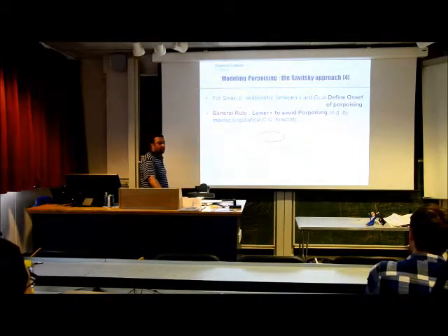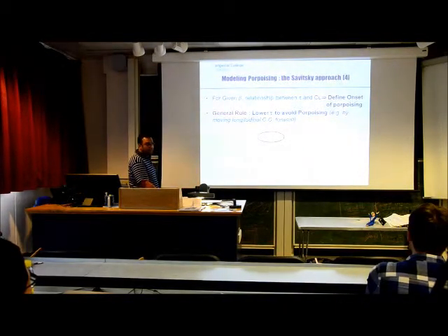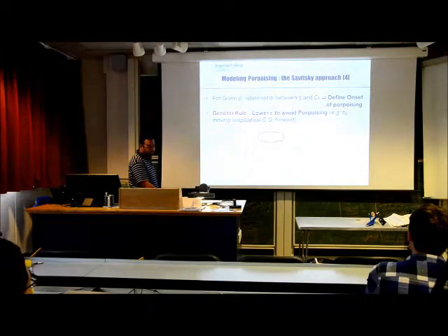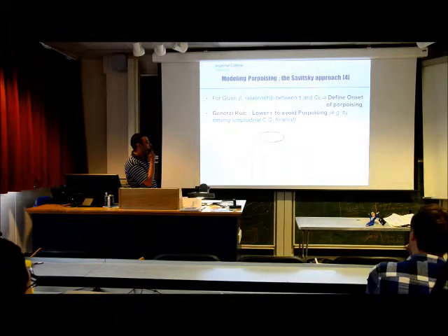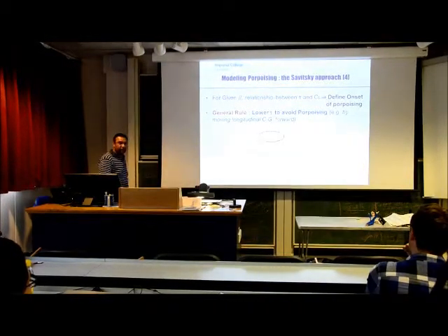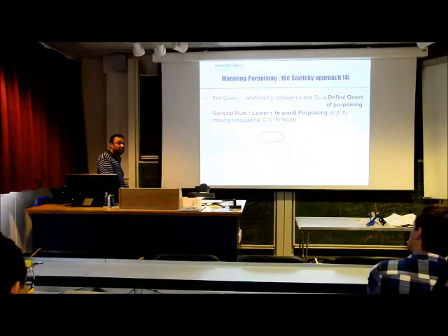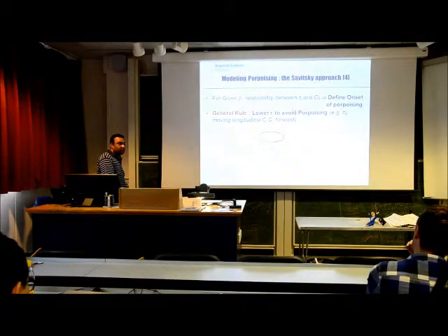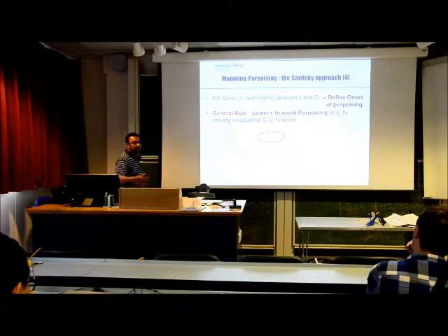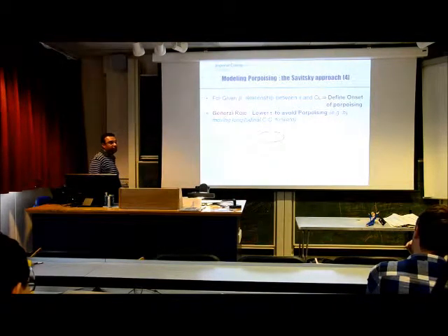Does this apply to hulls that have an afterbody, however? So you have something extending aft of your center of gravity. Would that still apply to that? Well, in the limitations I've found for the Savitsky, the criticism has been mainly about the absence of a tail, and the risk of extrapolating the Savitsky approach beyond certain Froude numbers as well.